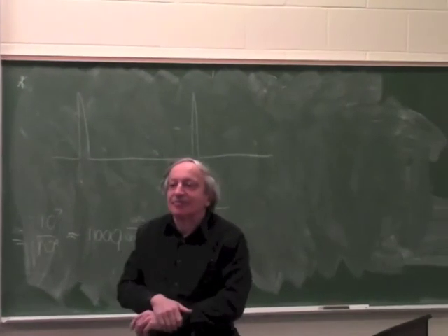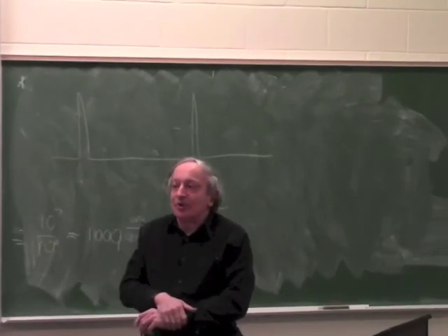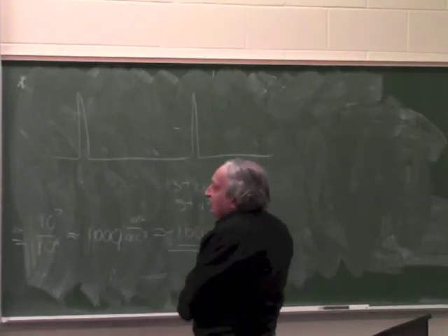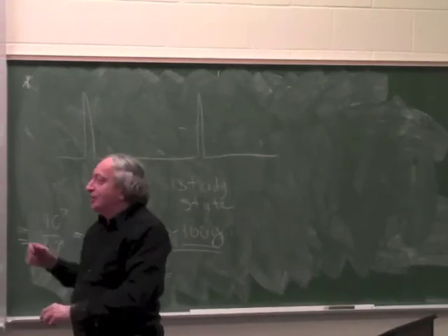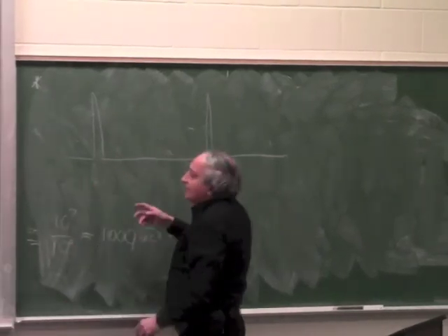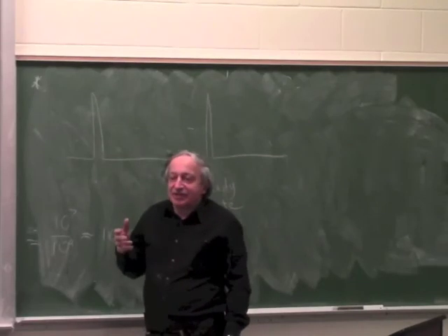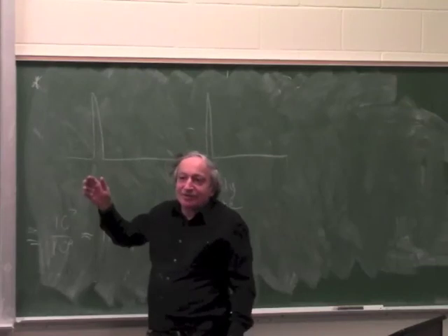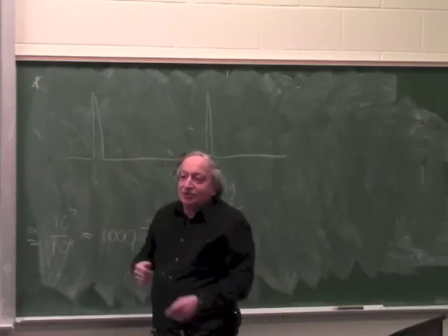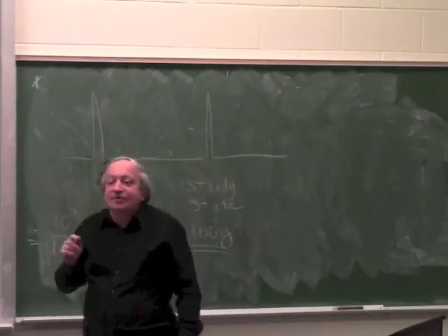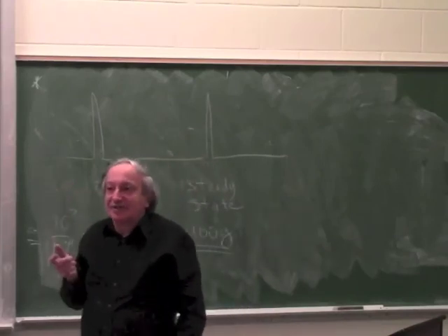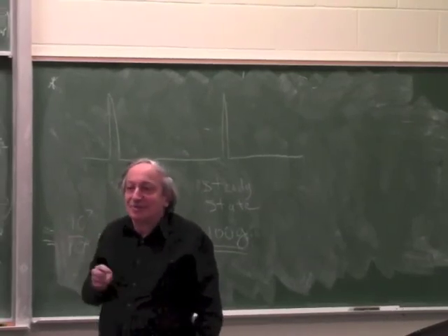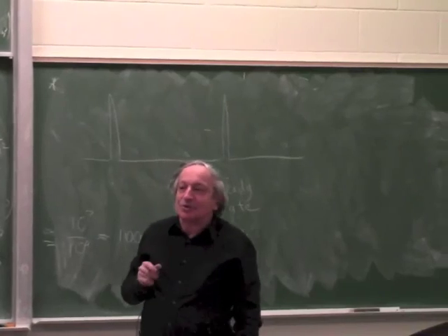Yes? Impedance. Okay, so that's a good point, but impedance you can overcome. The reason impedance is a good point is that any coil has inductance. So when I try to drive it very fast with a high current, the impedance will limit the rise of the current, but I can drive it from a current source. So solution number 1, I can drive it from a current source, then I don't see the impedance. Solution number 2, I can make the coil with very few turns of very heavy current. So drive it with thousands of amps, but have very few turns, and then I don't have much impedance. So the impedance problem has some solutions.